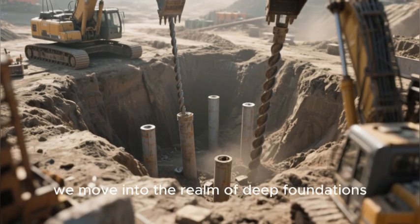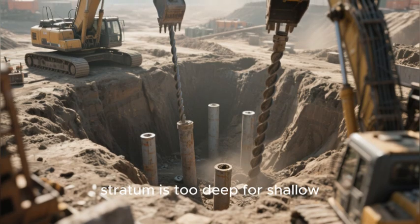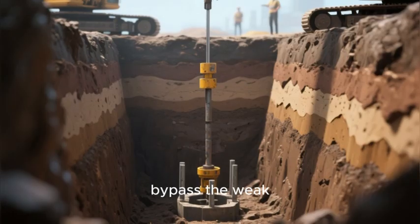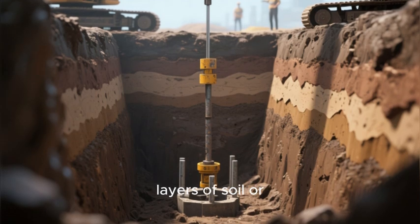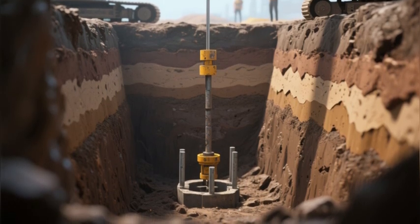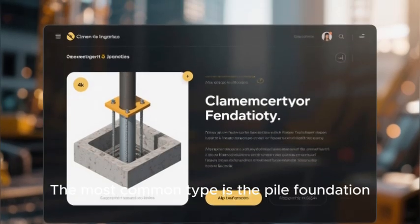Now, we move into the realm of deep foundations, used when the suitable bearing stratum is too deep for shallow foundations to be economical or practical. Deep foundations bypass the weak, compressible soil near the surface and transfer the building loads to deeper, stronger layers of soil or rock. The most common type is the pile foundation.